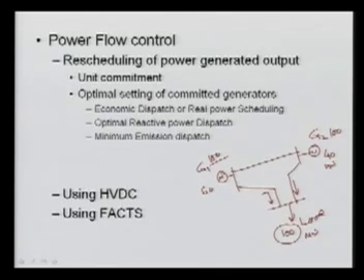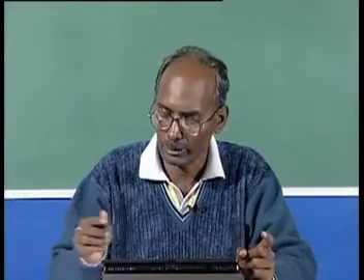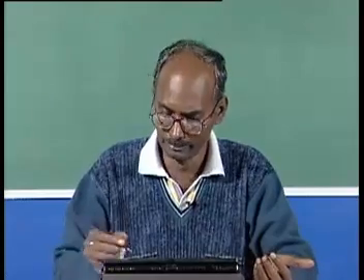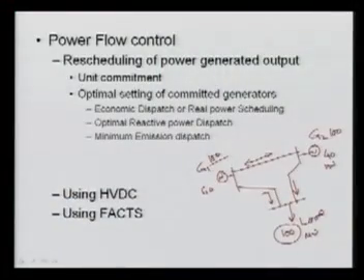Now, whether the current will flow here or in this direction, we don't know, and that is decided by the impedance of these lines itself. So you don't have control, because these lines are constructed. Once these lines are constructed and you add the generators, the current will follow the minimum impedance path and come to the load centers, and the total is balanced, of course. Here 60 megawatt, 40 megawatt and 100 megawatt. Of course, generation will be more than the load, always, because there will be some losses in the lines.